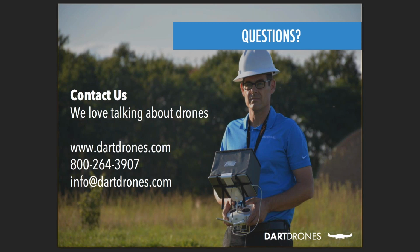One thing I would just add to that is, within DroneDeploy, a lot of our customers, when mapping large areas, the limitation ends up not really being line of sight. It's actually just the battery life of your drone. And so what's really common practice, and the app makes very easy, is you can fly until your drone runs out of battery while maintaining line of sight in one particular area. Once it does run out, it'll return to home, come and land.